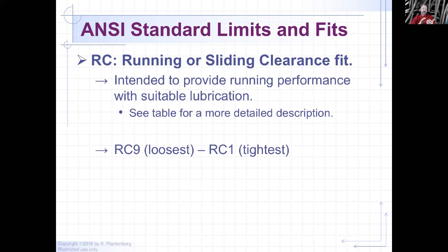So we usually lubricate parts, and then we want to have some clearance so that they can move, but you may not want them to move when they're going laterally, sliding this way. You may not want much slop in it, so it can't tilt.